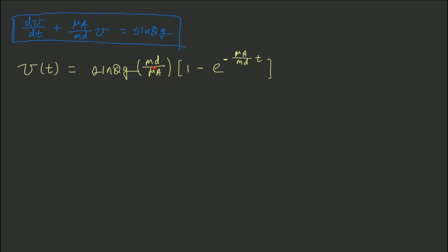Now, as the viscosity of the oil beneath the block increases, and as the contact area that the block has with the oil beneath the block increases, the steady state speed decreases. So a designer might derive an equation like this and look at these factors, and say, based on these factors, I know which factors are important in my design, which are not, and I can start to spec out the oil, the angle, the mass, the thickness of the oil slick, etc. You usually don't have much control over g, but that may change in the coming decades.